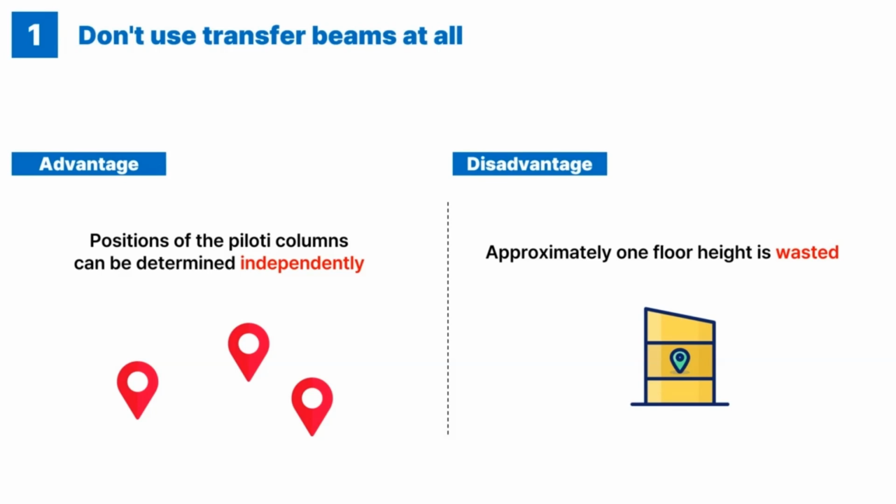However, to accommodate forming the rigid frame structure, due to the installation of transfer beams, it may require larger cross-sectional areas for the pilotis columns or additional pilotis columns. As a result, this leads to lower space utilization, increased construction costs, and longer construction periods as disadvantages.